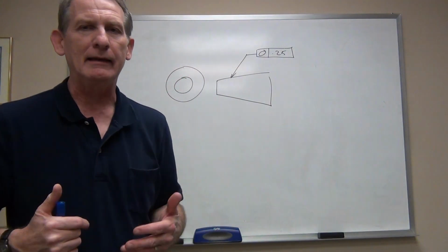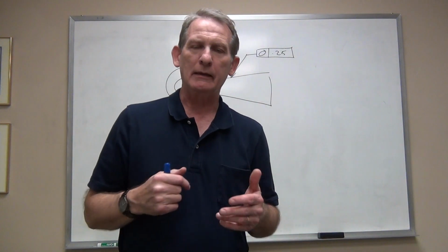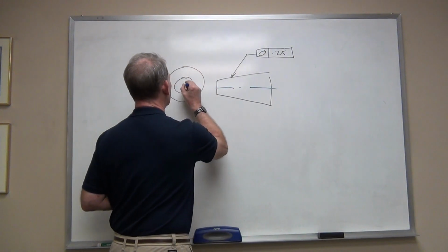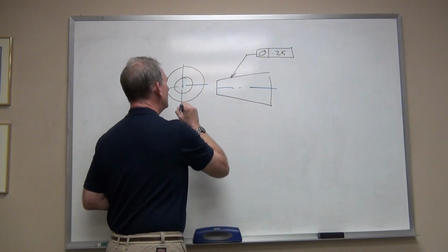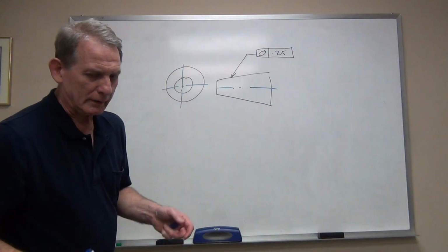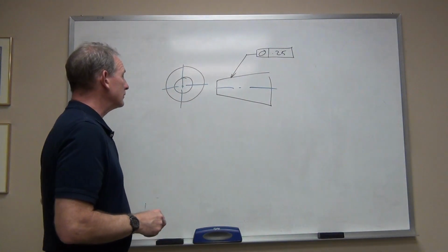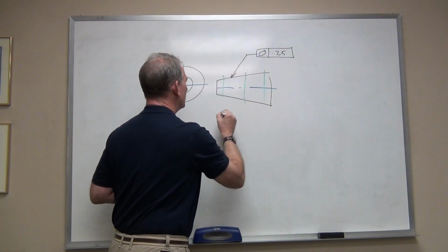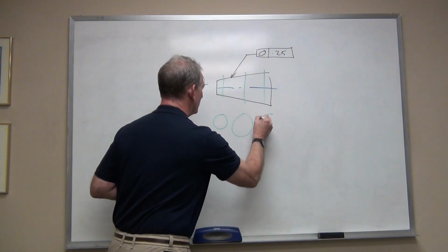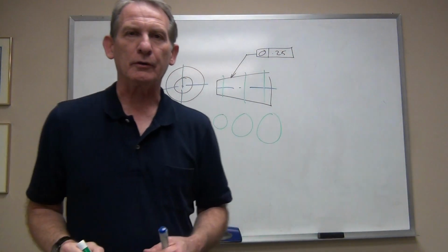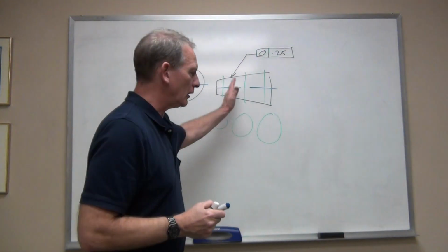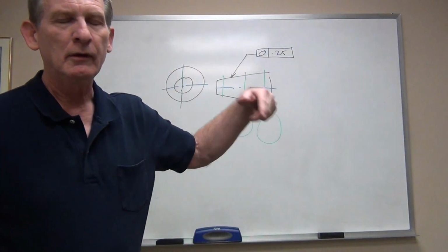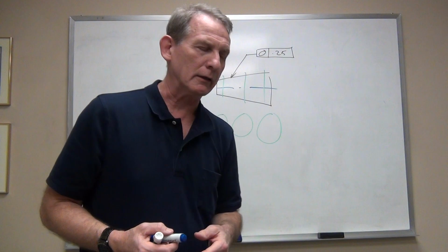In fact, any shape that can be produced on a lathe can have a roundness call out. And it's because if we take a slice through any section on this, we'll end up with circles. So down the length of this shaft, any section that we care to measure at that location will be a circle, and we can check its circularity.